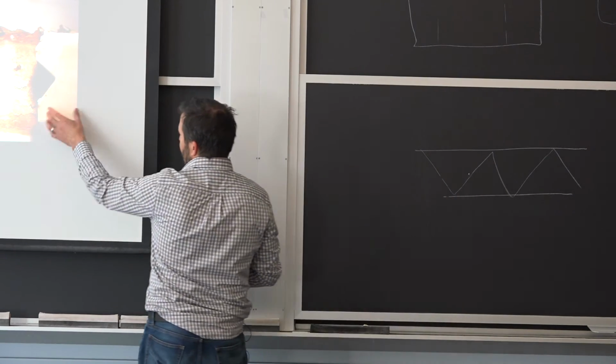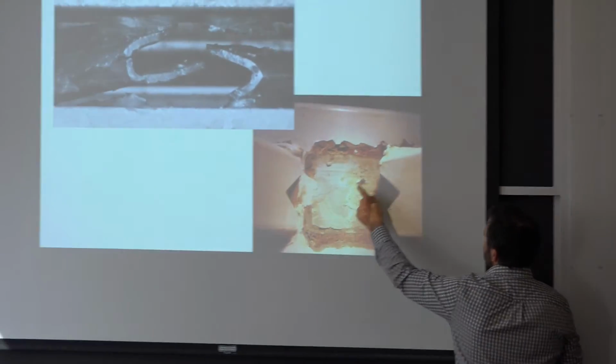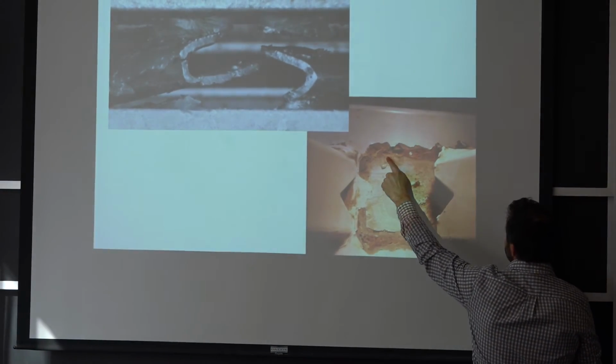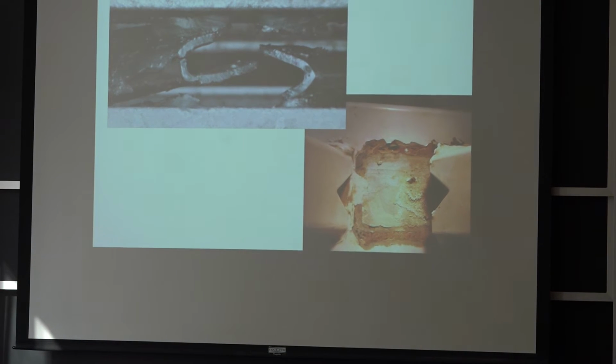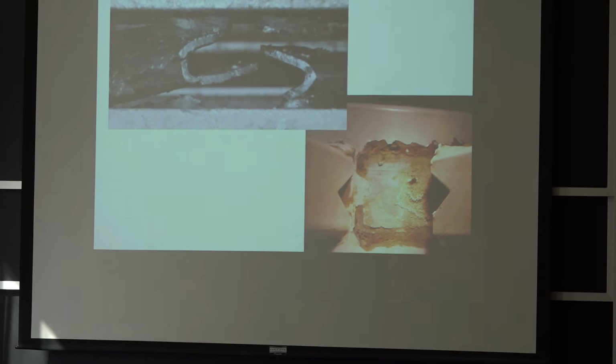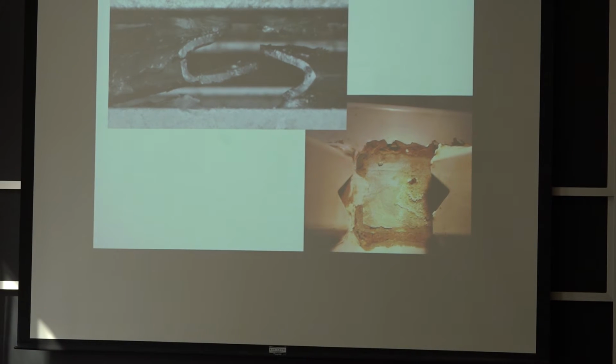So this is a diagonal here on a tube, a completely different project. It didn't fuse here. It only had a little bit of bite. You see the roughness in the corner here. That's all that was penetrating into the material, so it held for a couple of years, and then it broke after there was enough load or cyclic load.